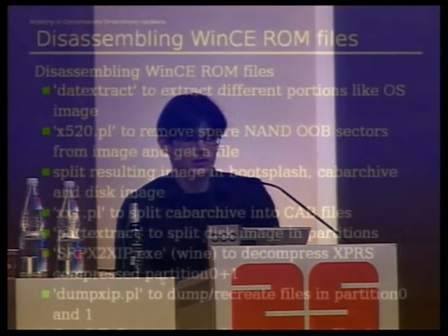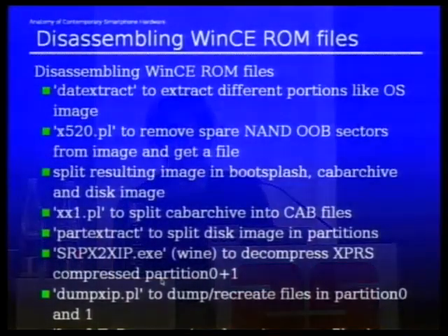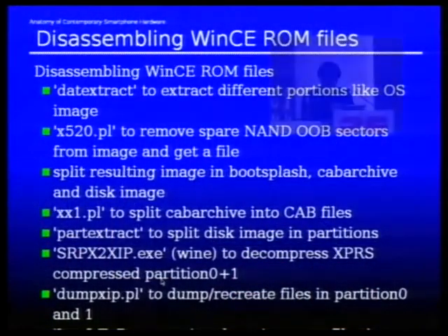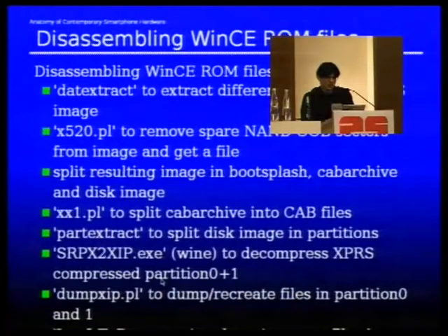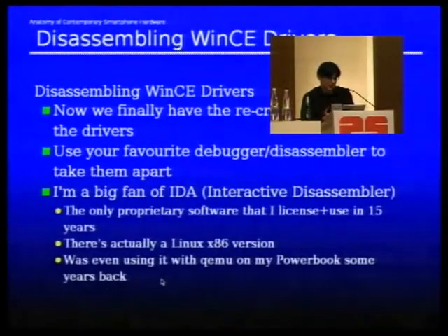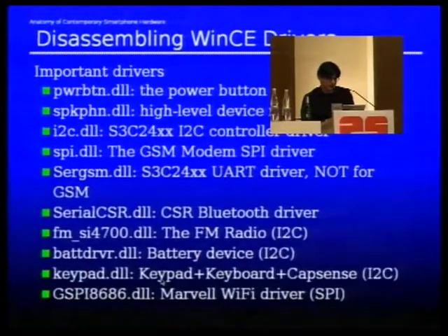Time is running quickly. Obviously, what you can do is disassemble the drivers. Before you can disassemble, as in assembly language, the drivers, you actually have to disassemble, as in unpackage, the Windows CE ROM files, which is a very unpleasant exercise. These are the kinds of various tools and scripts I had to use for the Glofiish, like spending a day in the hex editor and trying to figure out what they did. And then in the end, you might get the actual DLLs, or might be able to recreate the DLLs for the drivers, and then you can use IDA or any other disassembler of your choice and try to find out what's happening. These are the kinds of drivers that I was looking at for the Glofiish project. By now, I think there is very little that I don't understand in that hardware.